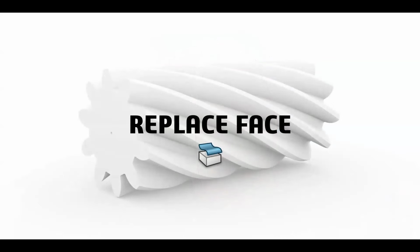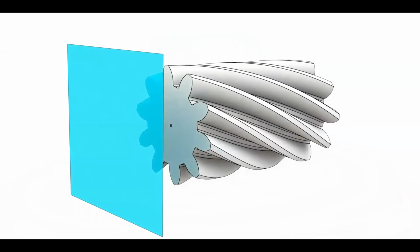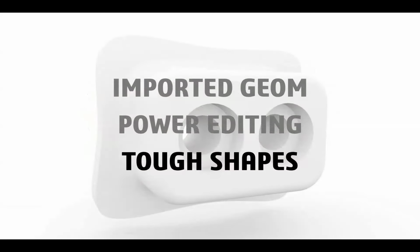Even with something like this, this is an imported helical shape, right? Stick a face out here a little further and use replace face and it extends everything out, even though it's still flat. Continues all those faces out. Try to extend that thing, if it was imported, it's a little more difficult if you don't know about replace face. Can't just stretch it.